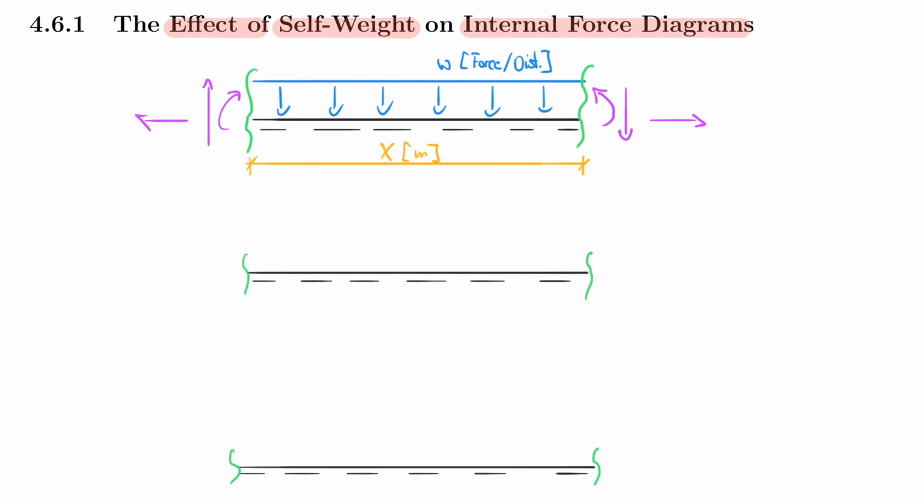And remember something that we discovered last class, that we actually have a relationship between the different cases. And one of the first ones that we talked about was that the shear force is really equal to the derivative of the moment. But another one that we also introduced is that the load case, let's call that minus W, is equal to dV/dx. And we can now think about what that means in the context of the evenly distributed force here and how that impacts the internal force diagram.